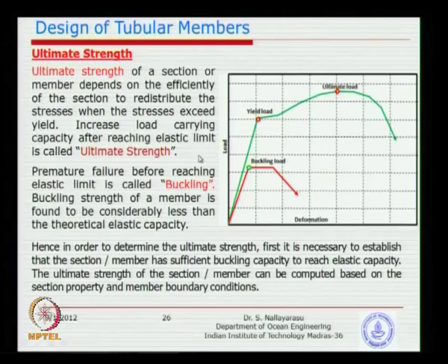It is related to the dimensions of the structure, both in terms of length and the geometry. Now, if you look at this green line, because the column is probably too stocky, too small in length, it never goes into the buckling mode. That means it keeps on carrying larger load until it gets compressed, isn't it? So that is where we call it the yield is governing the design.